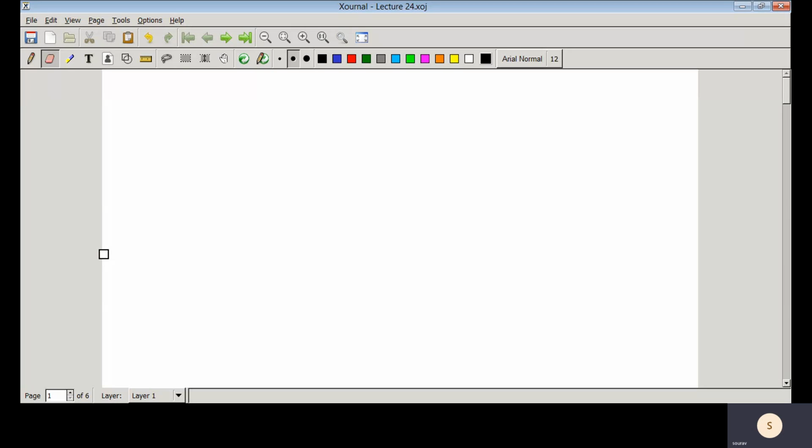This is lecture 24. In the last two lectures, we have discussed the Nyquist stability criterion. If we have the information regarding the loop transfer function poles, and we know how many encirclements there are in the counterclockwise direction about the -1 + j0 point, and they are the same, that means N is equal to P, then Z would be equal to 0, that means the closed loop system would be stable.